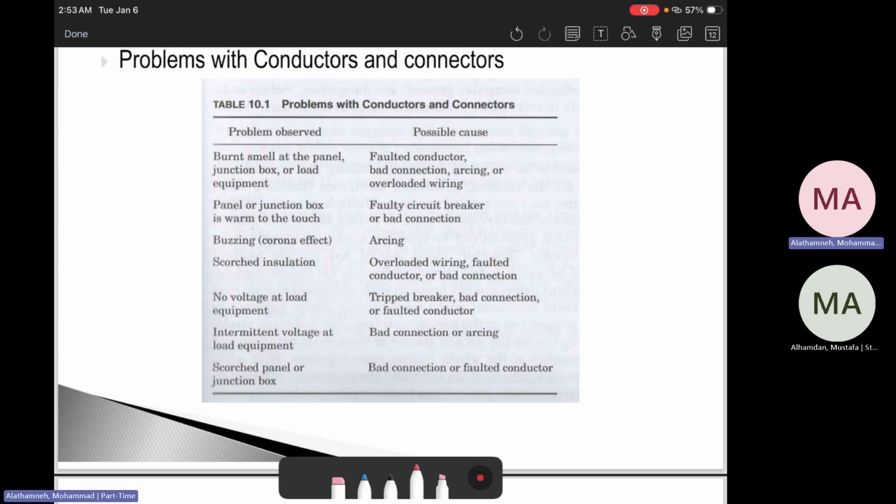Corona happens basically more in medium and high voltage systems. Corona effects can happen at the conductors, where you can see a blue light around them, while the buzzing is only in low voltage panels, and it is a red alert: there is some looseness in the neutral or something going on in the board. It is basically either an overloaded connection, heating; fires may start exactly this way.